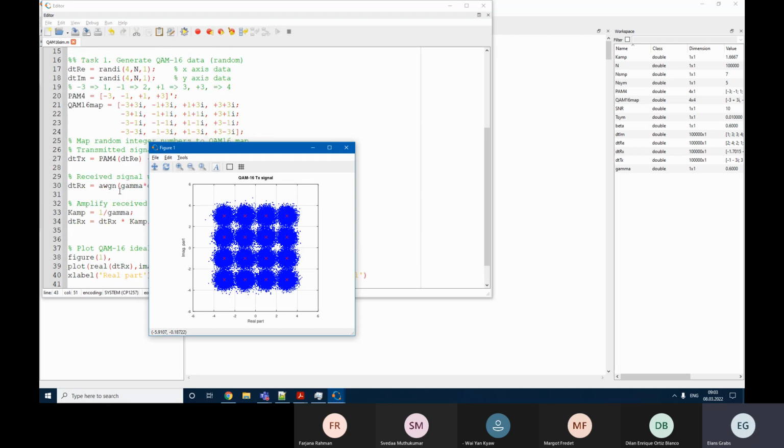What we want to do next is to demodulate the signal, to detect signal, yes. So basically each point, for example, this point or any other, is then accordingly evaluated by distance or metric to all the possible real points, yes? And accordingly, as it should be clear from intuition, yes, the correct point is assumed to be the closest one, yes?